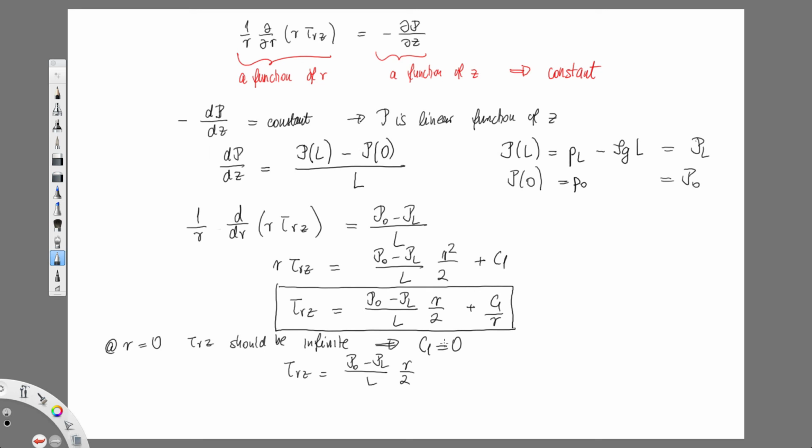So I can have a 0, just a value of shear stress evaluated at one point, there's no problem with that. I cannot have an infinite value physically. So basically this is a linear profile. I get a 0 in the middle, and I maximize in absolute sense on the sides of my tube.